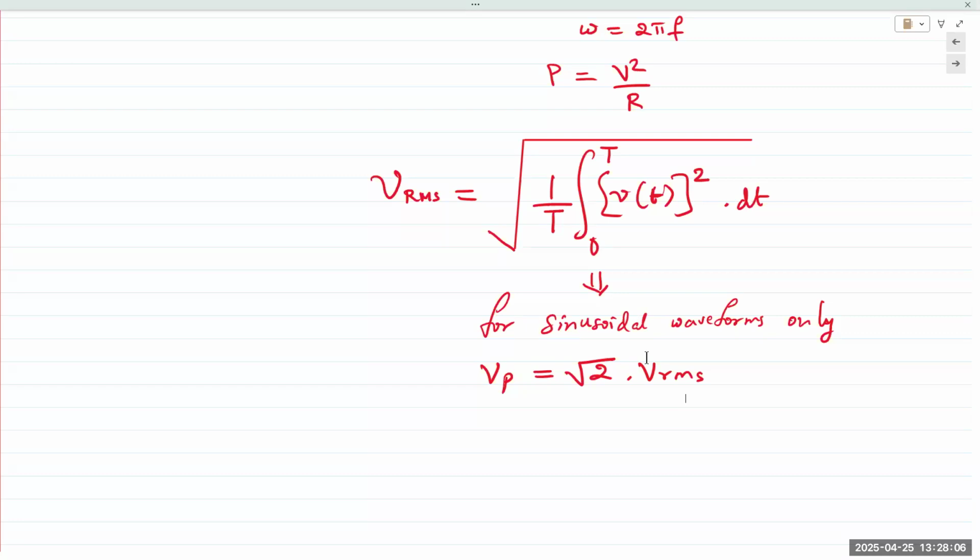So the reason peak values are important is because electricians and engineers need to know what is the maximum value of the voltage or current that is flowing through your electric lines. Okay, the effective value is RMS, but that voltage or current is still reaching that peak value. And obviously it's very fast, it's 60 times in 1 second, but that peak value is very important. That's why we use both conventions, peak to peak and RMS. Yes.